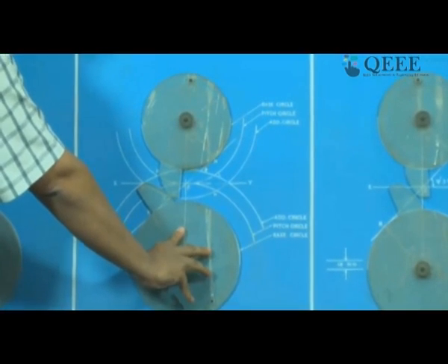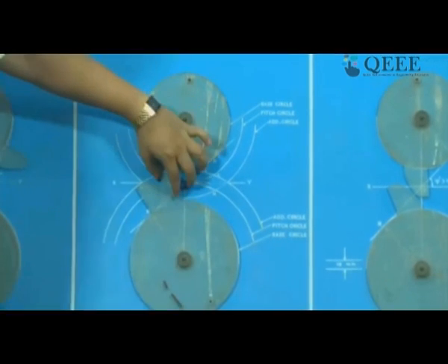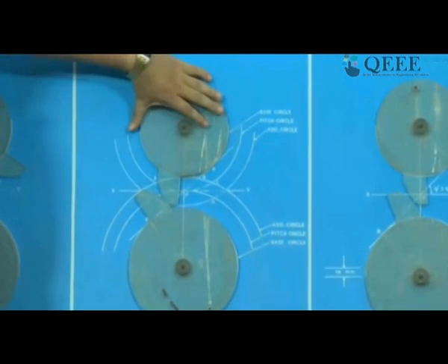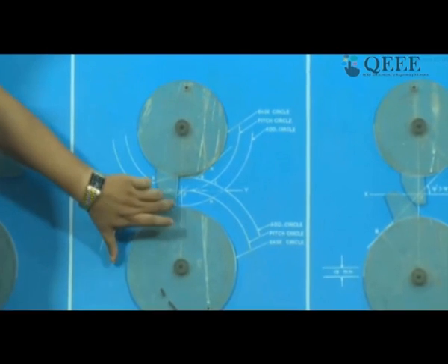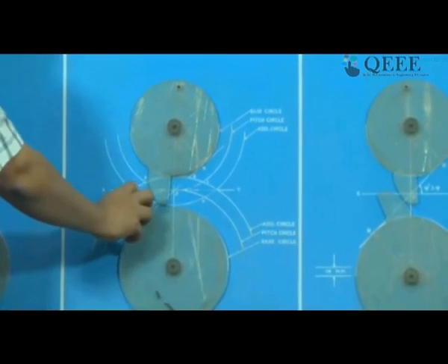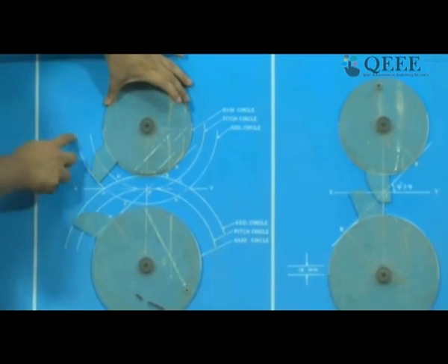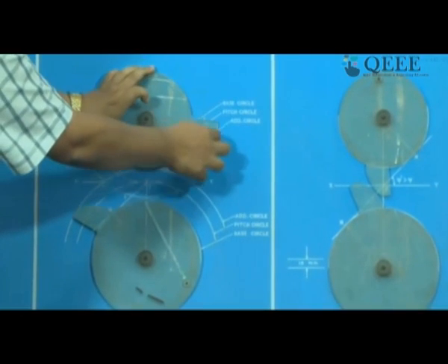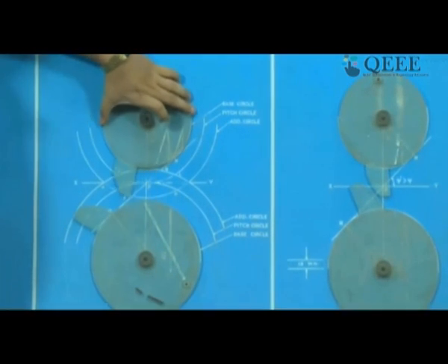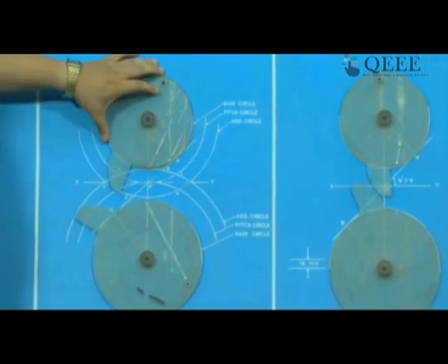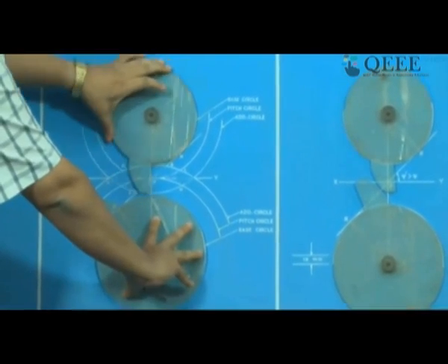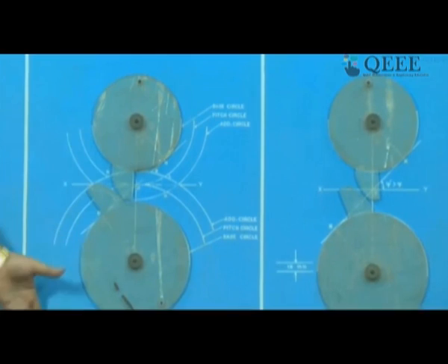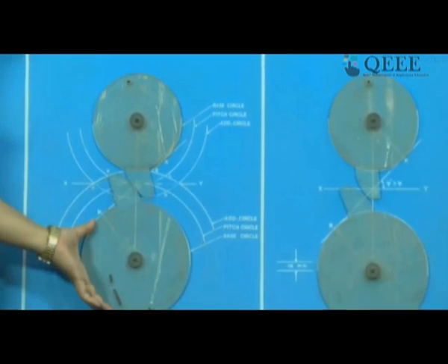And how do we identify this point? This point is identified where the extreme uppermost or outermost periphery of this gear has just come in contact with this body. This circle is the addendum circle of this top gear, and you can see that the outermost periphery is tracing this white line, the addendum circle. Wherever the addendum circle of this gear is for the first time contacting the tooth profile here, there you have the first engagement. So this is the first point of engagement.